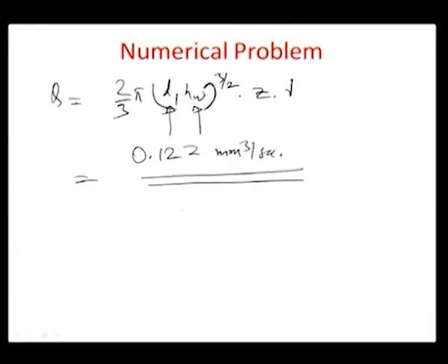So this is not really a very high amount, as is obvious from some of the conventional machining processes, where it can be hundreds of cubic millimeters of material coming per second, okay. So therefore this process, although on a comparative basis with a conventional process may not yield a very high material removal rate, does have a very high surface finish, and that is one of the reasons why, from a microsystems fabrication standpoint, where material removal rate may not be the key component, what does play a significant role is the surface finish.